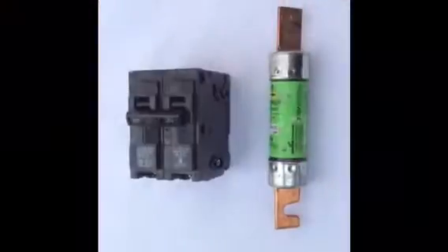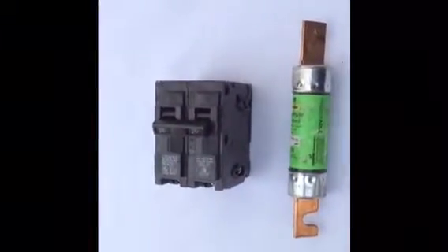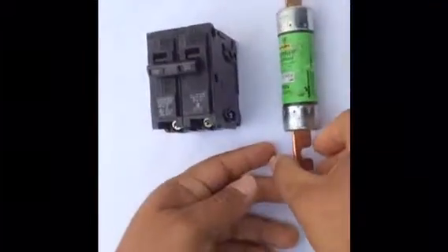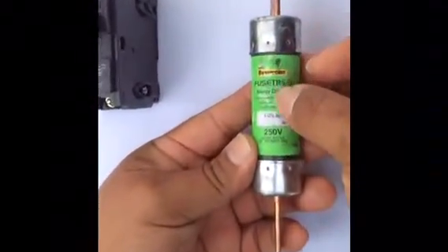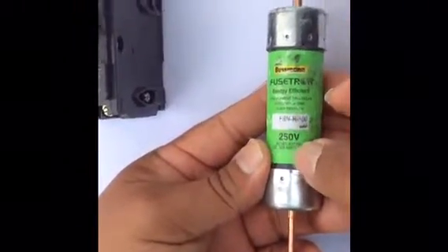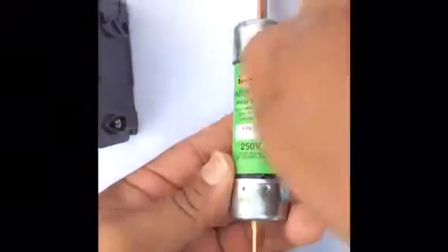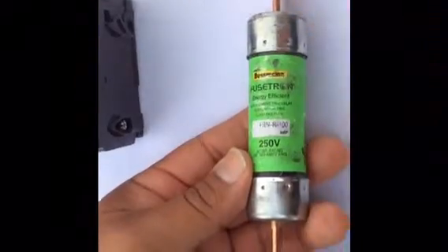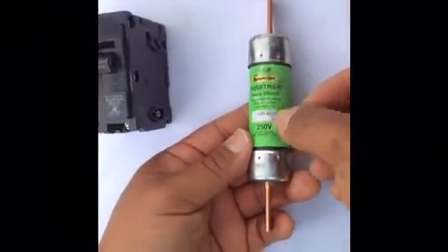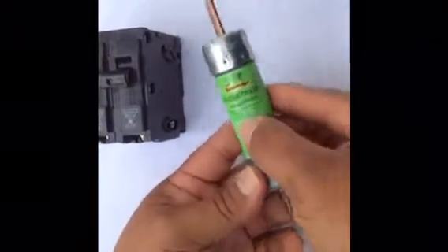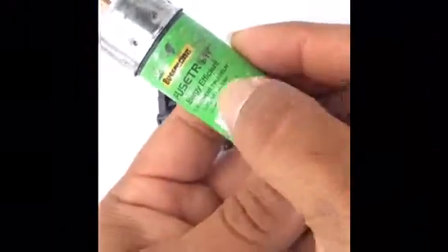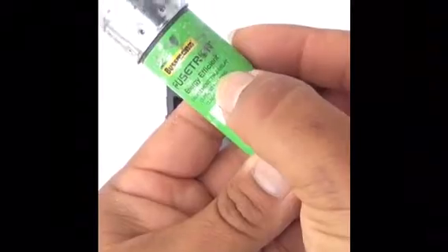Okay, so a little more in-depth information on these current protection devices. This is a fuse. Inside there's an element or a metal link which, when it experiences an overcurrent, heats up, opens up, cuts the power, protecting our conductors, equipment, and so on. This here is a dual element. I don't know if you can read it or see it, but it's a dual element.